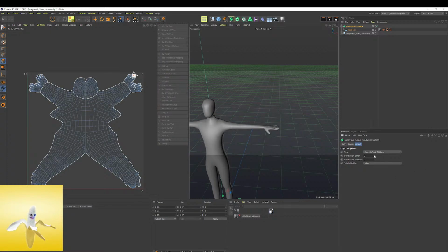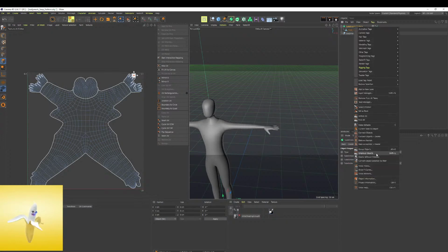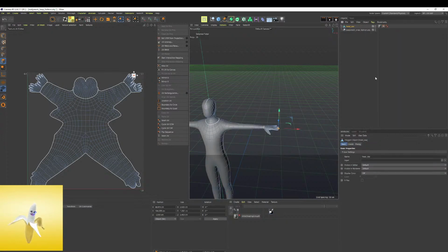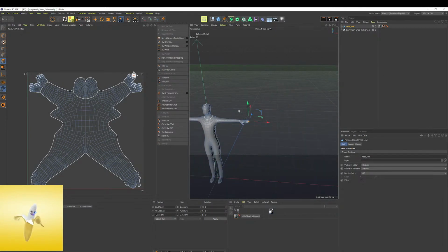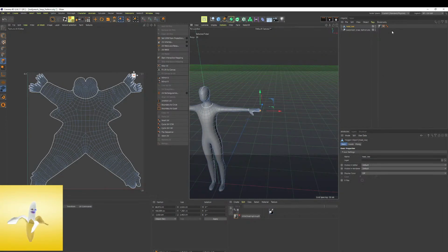And we can increase or decrease the number of polygons. I might just go down one level so it's a little bit less heavy, and it will load on more devices, including older Android devices on Snap and on Instagram. Haven't decided which one I'm going to put it on yet. Okay, so this looks like it's all ready to go. So we're going to connect objects and delete. So now we're just left with one giant object that's unwrapped, and it's got some good UVs.